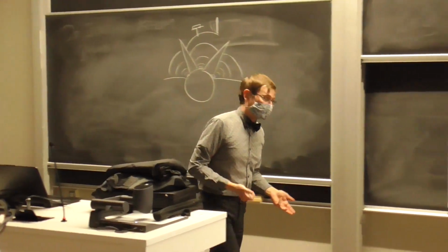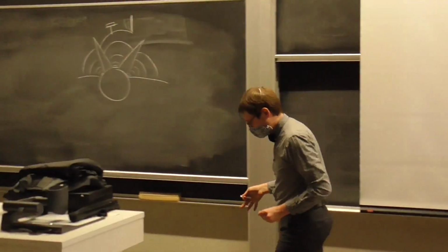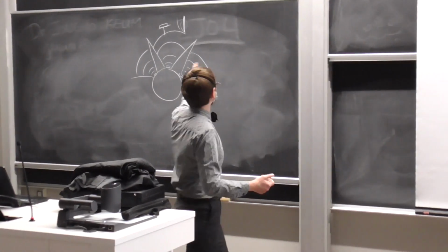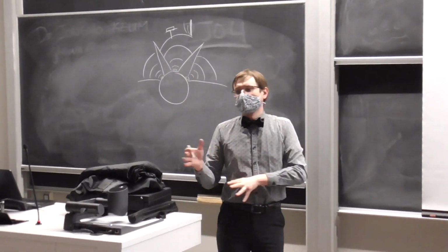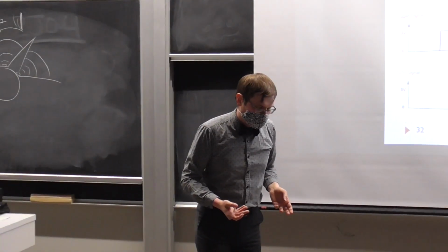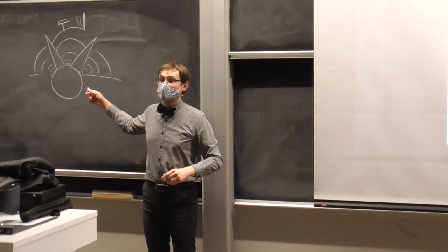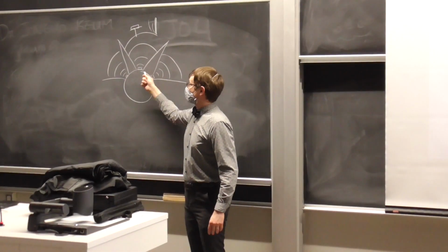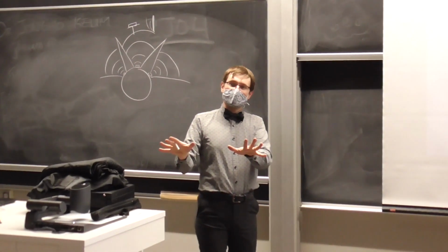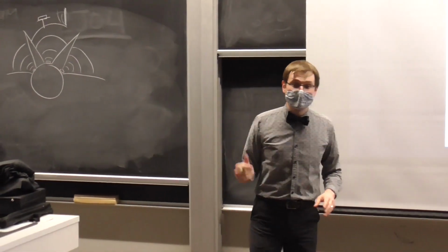These are the sorts of things that we're still working out. So ultrasonic sensors are pretty good, but they're not super reliable, particularly for stuff like that. They are probably better than they used to be, but yeah. Another way that you can prevent these guys from interfering with each other is to stagger them. Test this one, then test that one, then test that one. Pulsing all of them at the same time is probably a bad idea. You would want to do them one at a time.